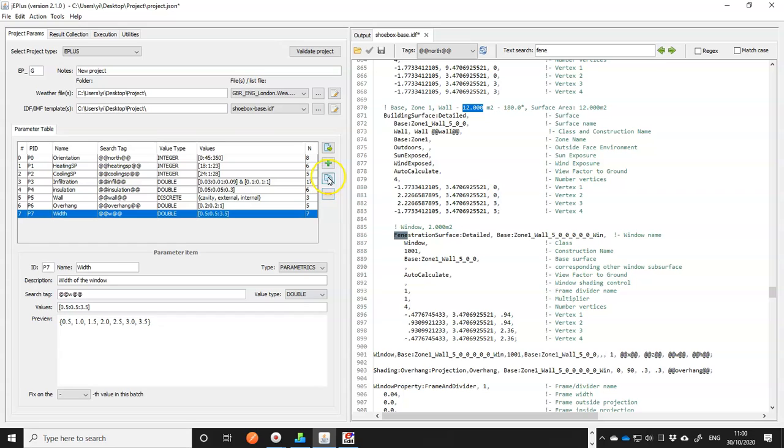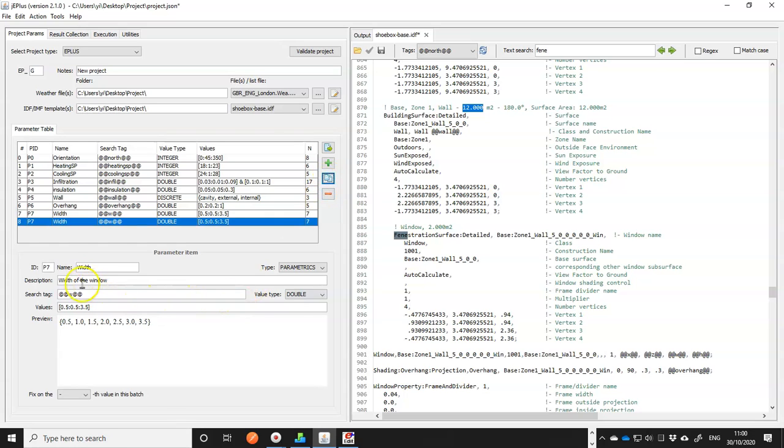And similarly, we can add height. I made a copy of the previous one. If you do that, remember to change the ID, because you can't figure out the ID automatically. So this is height. This one will be H. And it's 3 meters high for the wall. So we reduce this to 2.5 meters. So the maximum height of the window should be 2.5 meters. Right. So we have the parameter for width and height defined.